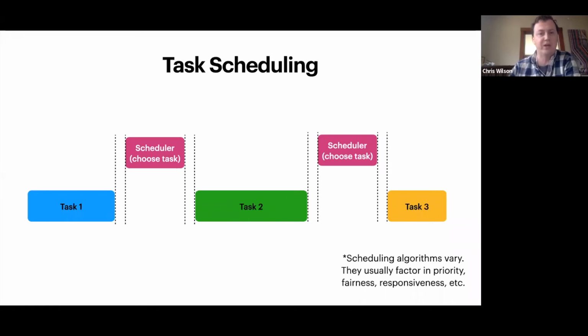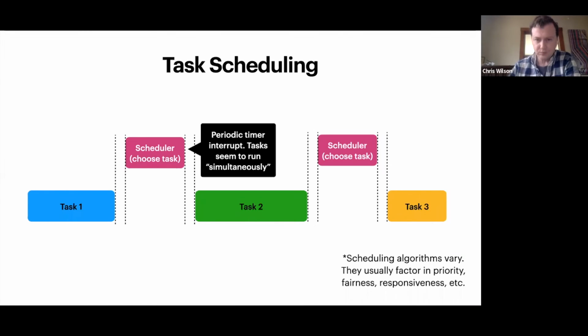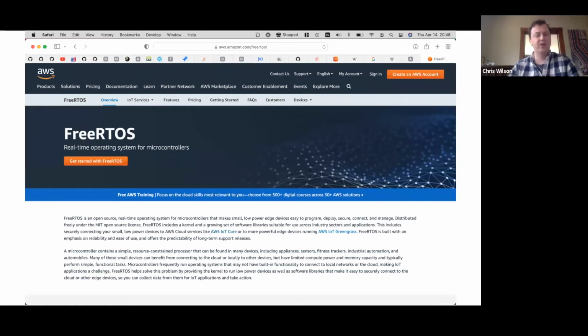And if you keep going down this road, you end up getting what's known as an RTOS, or real-time operating system. You can think of it as the most stripped down, bare bones version of an operating system, where it's really just concerned with running these separate tasks and scheduling them. Maybe it'll have some functionality around sending messages between tasks, so it might have a queuing system, or mutexes to protect shared variables, things like that.